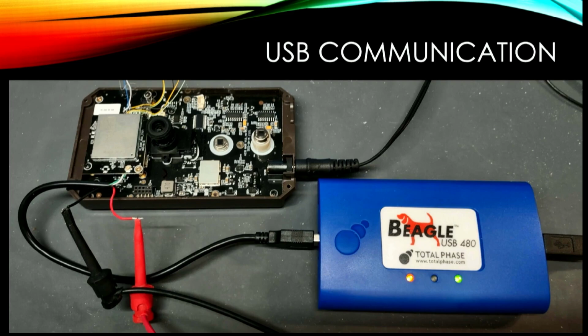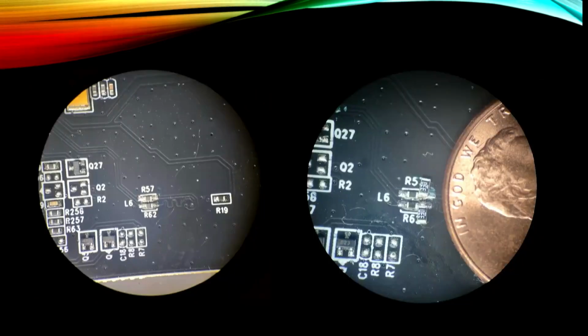So you just lie to the Beagle. I set up a 5-volt power supply, a little one you plug in, and I just hook 5 volts to it. So it says, yeah, there's a device there, of course. And it works pretty good. But to connect to it, you can't connect right to the USB lines. You'll instantly overwhelm it.